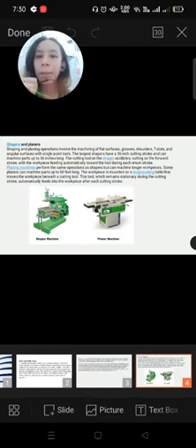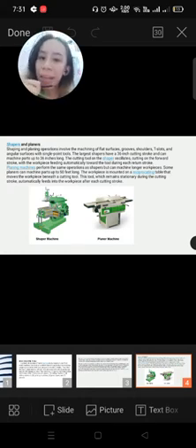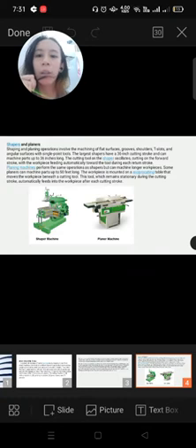Planing machines perform the same operation as shapers but can machine a longer workpiece. Some planers can machine parts up to 50 feet long. The workpiece is mounted on a reciprocating table that moves the workpiece beneath a cutting tool. This tool remains stationary during the cutting stroke and automatically feeds into the workpiece after each cutting stroke.